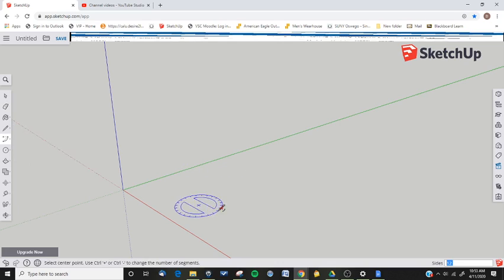So begin, same thing as any other of the tools that we've really used. You have your first click, which helps start the whole process off. So this pointer is allowing me to determine where the start of my arc is and how far out I'm going to be. So this is the length away from that center. You can see again down in the lower right hand corner. So let's go about 8, almost 9 feet. And then that allows me to determine how much of that arc, and you can see an angle measurement in the lower right hand corner. So let's go 90 degrees. There's a 90-degree arc right there. Set away that length that we originally had from the center, and you can see how it pops up again right there. So that's our first one. So I'm going to get rid of that.